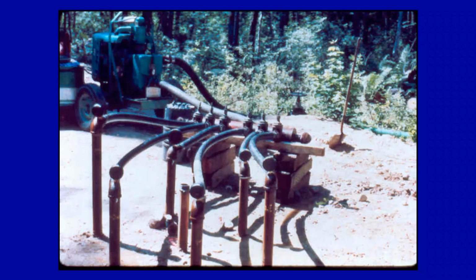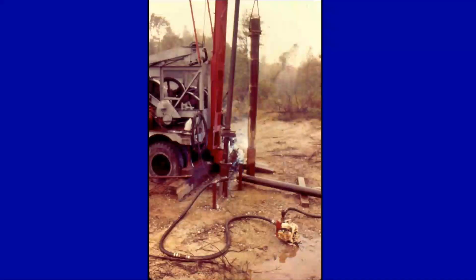Well, this is an example of one of the methodologies used to run and conduct the pumping test, which is usually the second stage after a favorable test well has been found. Rather than putting an 8-inch or 12-inch diameter test well in the center, if it is particularly shallow, more water can be pumped by putting in a group, usually a hexagonal group with one observation well in the center to check what the drawdown is going to be. However, we can also put in an 8 or a 12-inch well. Now, I had indicated that we usually put in a test well and 2 feet away an observation well.